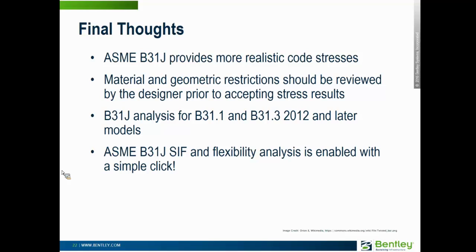So there's some more confusion on the crotch radius. They're saying we got some comments that they don't deal with the pipe manufacturer until they actually purchase the piping and such. But the crotch radius is usually publicized material for standard fittings, and if you have to fabricate the fittings, you're going to have to measure those crotch radiuses yourself. Do you have any other comment on that, Josh?